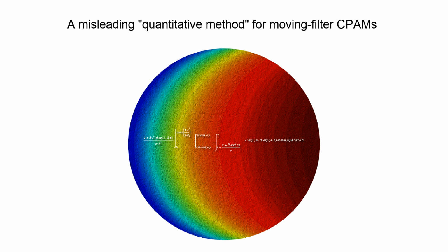However, realistic or not, it has for decades been the practice of CPAM vendors to provide a set of curves, graphs, based on the expressions above. Such graphs have concentration on the vertical axis, and net count rate on the horizontal axis. There often is a family of curves, parameterized on the detection efficiency, or labeled as to specific nuclides. The implication in providing these graphs is that one is to observe a net count rate, at any time, enter the graph at this value, and read off the concentration that exists at that time.